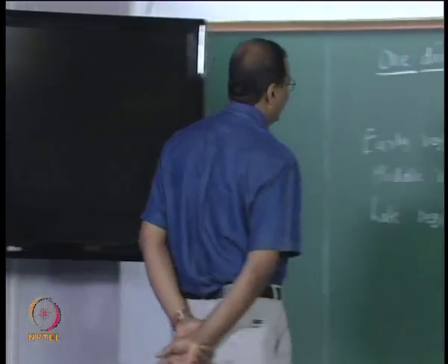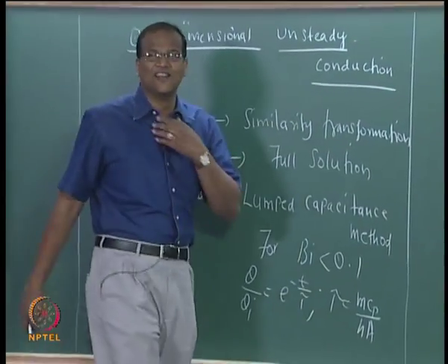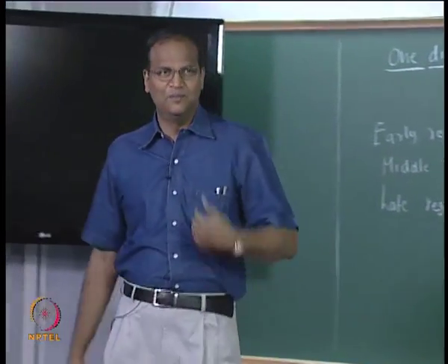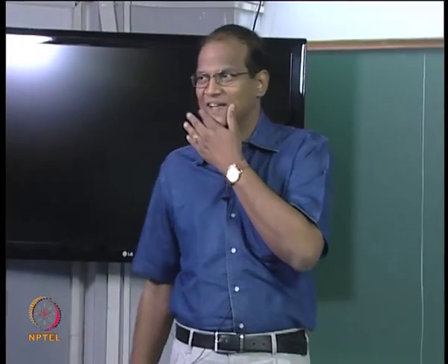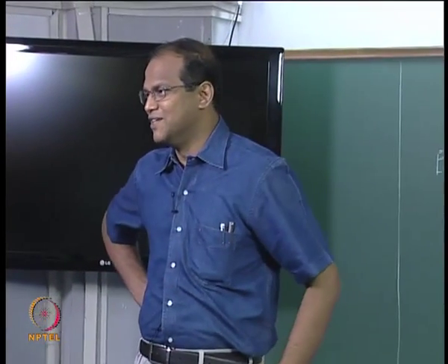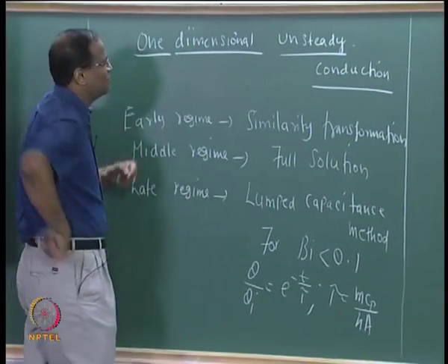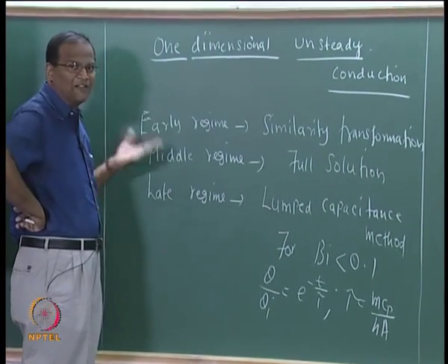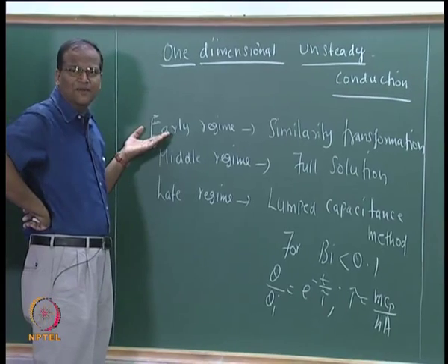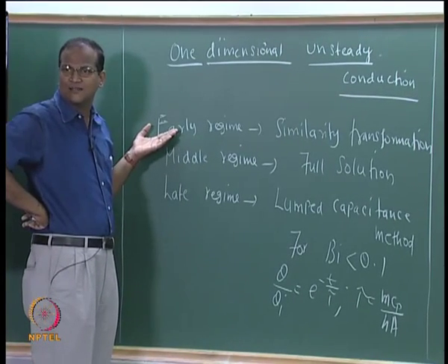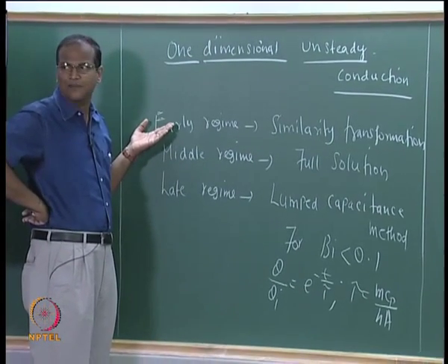It is topical that we are looking at transient conduction, where things change with time, as with any other situation in life. So in fact this is beautiful. Yesterday we saw the one dimensional unsteady conduction. We can have 3 regimes. In the early regime only a certain portion of the solid is affected by the thermal disturbance at the boundary.